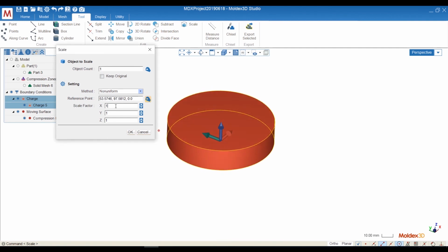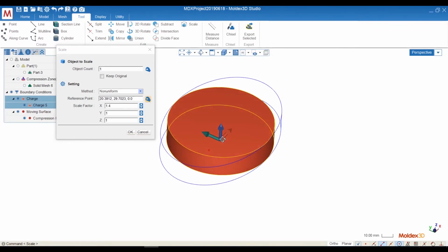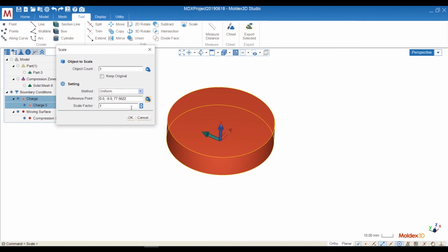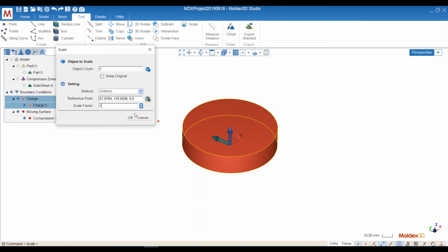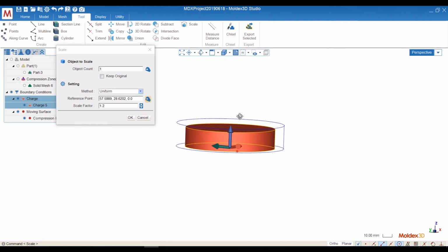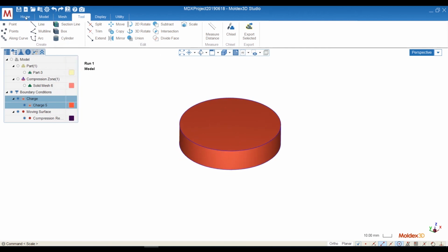So on each direction we can have a different scale percentage. So for example, right here we can put 40% bigger along the X direction, and immediately we'll have a preview. Or if we change it back to uniform scale, since our part is 144 and it needs to be, let's say, 80% bigger, we'll give it 20% bigger on all three directions. So this is our new charge.